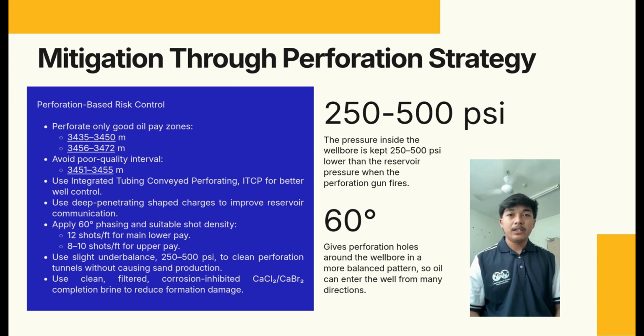Third, formation damage will be minimized by using integrated tubing conveyed perforating or ITCP with clean and filtered CaCl2 or CaBr2 completion brine. This fluid is low in solids, stable at high temperature, compatible with sandstone, and corrosion inhibited.